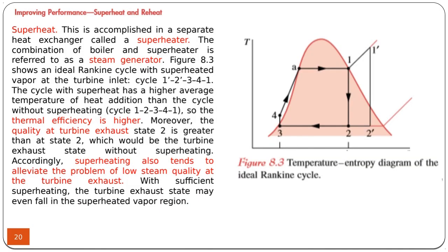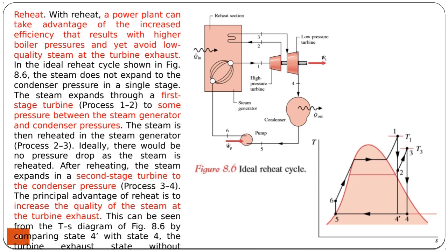So it's possible to superheat the vapor inside the boiler, so that instead of using a saturated vapor, you can also use superheated vapor. The efficiency of a superheated vapor boiler is higher than the efficiency of the saturated vapor. Another addition would be reheat.